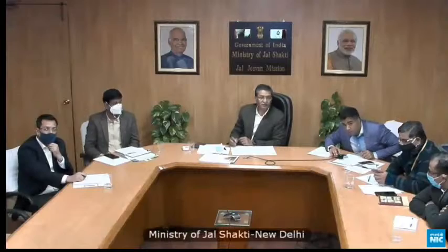Due to the alluvial nature of soil in the river basins and humid atmosphere, sludge drying beds are not at all effective, sir. Neither can we dispose the residual sludge to any natural water bodies, nor can we dump it somewhere else. Regular disposal of the sludge to longer distances by road carriers, truck carriers, is not economically viable for a water supply project, sir.